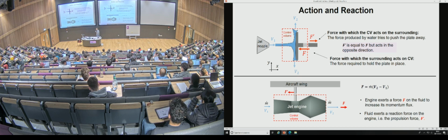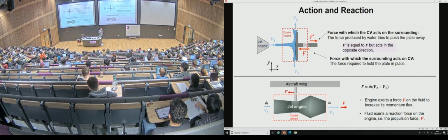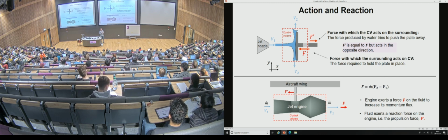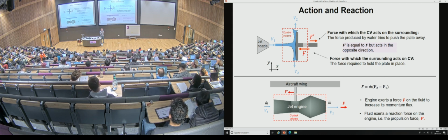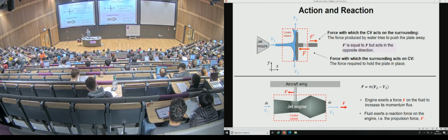In a jet engine, you have fluid propelled one direction, which imparts an equal and opposite reaction in the other direction, which is essentially the thrust. Right? Propellant ejected, you move in the other direction. In this case, the engine and the support are essentially the same thing. It can't move. So the force is transmitted through the support, and so the reaction is in the support going in the direction of the thrust. There's a question we'll look at about this as well later.